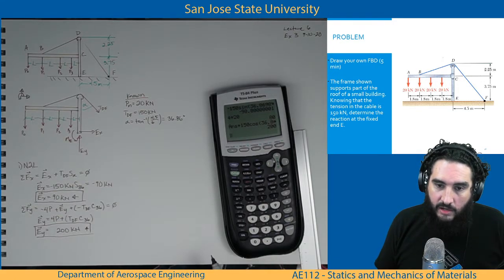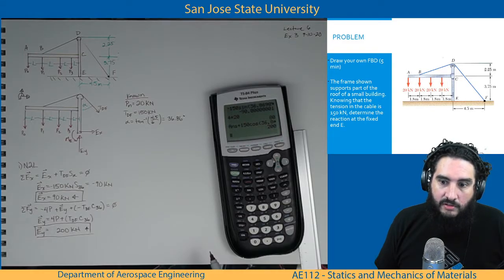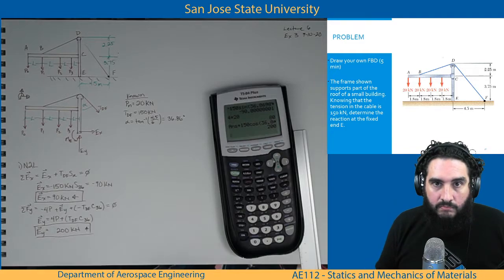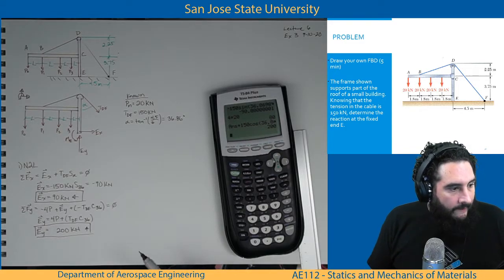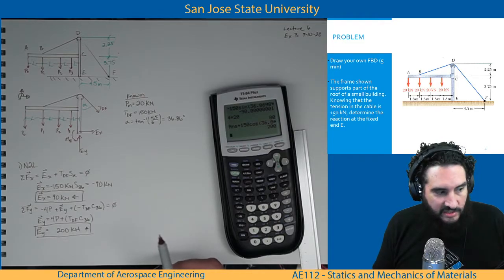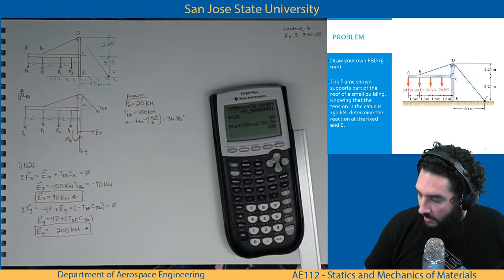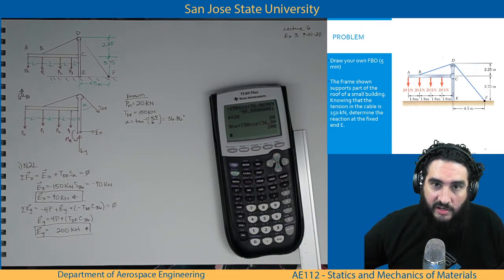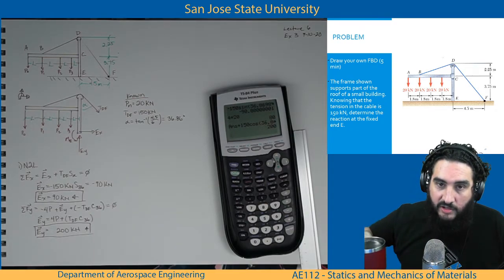I could ask you what are the reaction forces at C, and since it's rigidly attached, you could either take the moments about member AC or DE and find out what happens at C. But for this problem, they're part of the internal of member A, B, D, C, E. No, C definitely does something. It just we're not interested in it right now, and so we have not broken apart the member into two pieces.